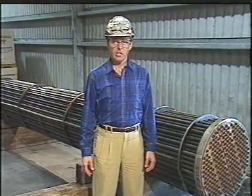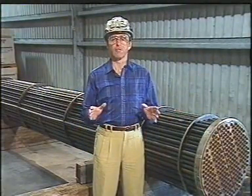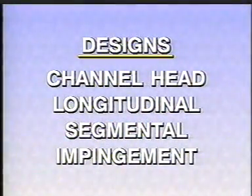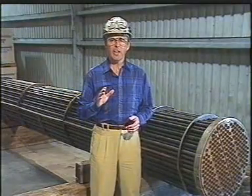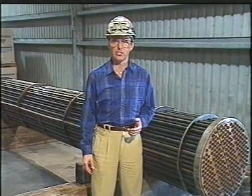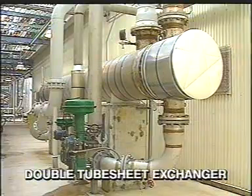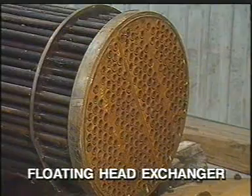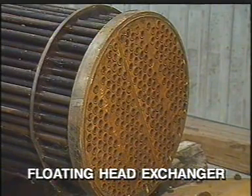We've covered a lot of material in this section dealing with the internal flow arrangements and problems that may occur. To summarize, there are several types of baffles that affect flow: channel head, longitudinal, segmental, and impingement. Expansion and contraction cause stress. This can be managed in several ways: with the double tube sheet to collect leaks, with a U-tube exchanger to allow for expansion, and the floating head exchanger, which makes cleaning and inspection easy.